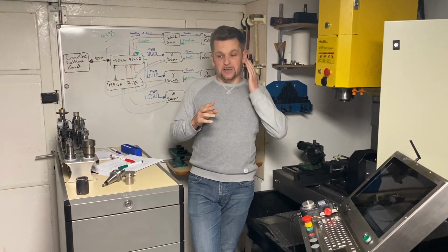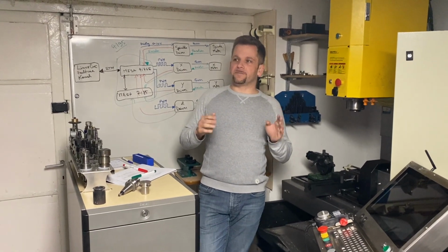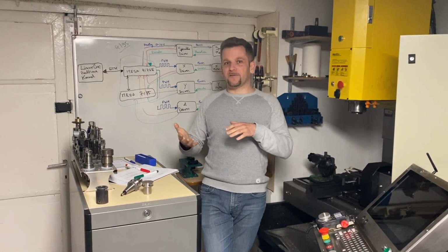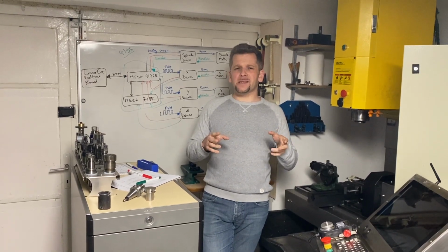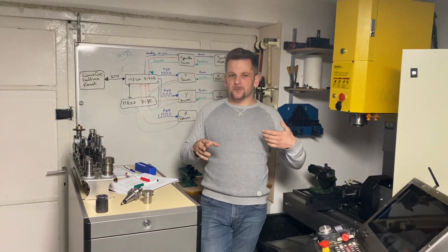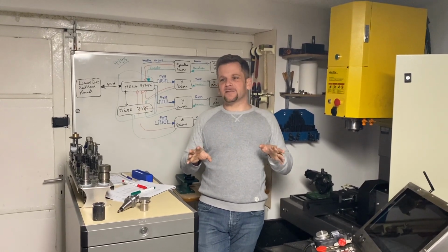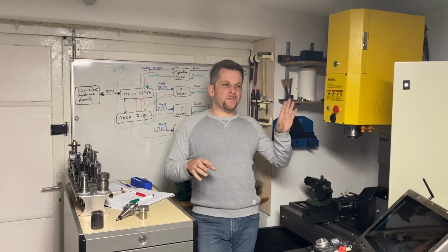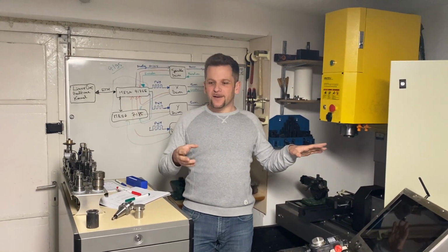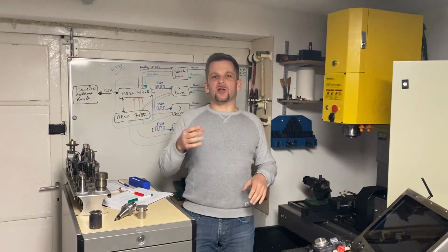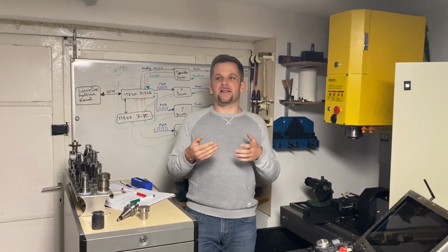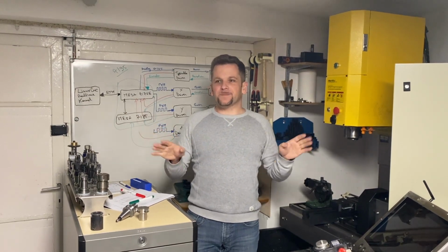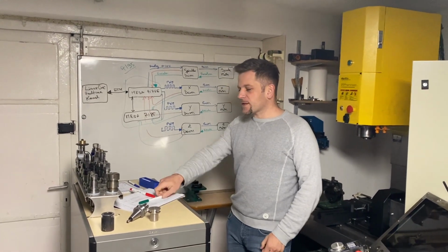I'm retrofitting a machine now, a Traub mill, and fortunately, or unfortunately, when I started, that machine has an absolute encoder, it has analog drives. So LinuxCNC was closing the loops. In that case, on that machine, my crash, the second one, would have never happened, because when I wanted to do the homing and the motors were not moving, LinuxCNC could notice that, hey, the motor is not moving, stop everything. Okay, so lesson learned.